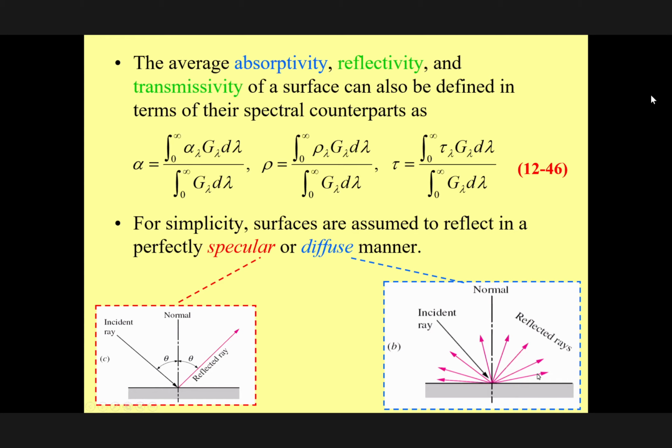Sir? Yes, sir. In what case would it be specular? Depends on the application that you have, my friend. For example, it depends on the characteristic of the material, if we are trying to design a material for a certain application. In reality, it is like that, specular. In reality, for simplicity in our calculation, it acts like this. In real applications, you can look at a building material, which may reflect in one direction more than the other. But here we assume it is diffuse in all directions.